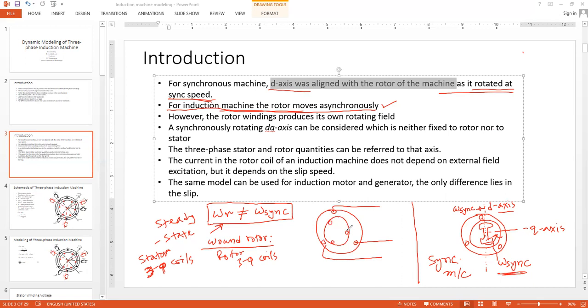Okay. So how would you start the induction machine? First, supply the 3-phase power. Excellent. That will create a rotating magnetic field because of the phase angle variances. With respect to this rotating magnetic field, the rotor bars are initially stationary, so there will be a current flow in the rotor bars. And due to the current flow, the rotor bar will have its own magnetic field.